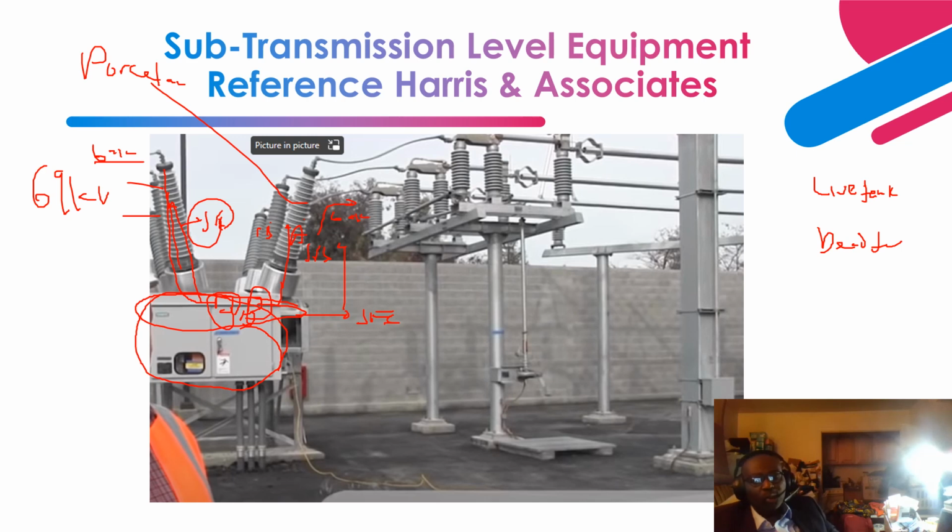I also have explained to you several times in different sessions the reason why we have this zigzag configuration of the apparatus bushing: it is to increase the leakage current path to ground, to prevent a flashover due to the buildup of leakage current.